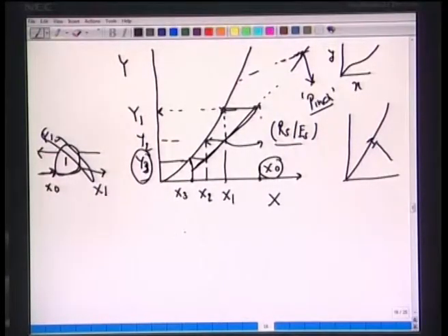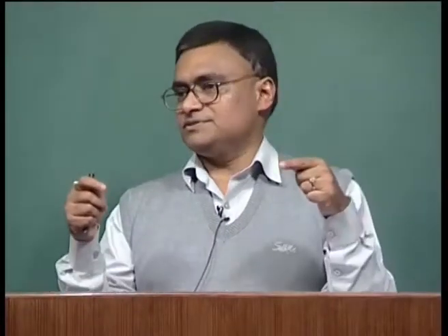Okay. We will also like to look at this entire counter current process slightly differently. If you have just one stage and we bring two streams, it does not make a difference where the inlet ports of these two streams are. So if you have one stage, they can come in contact like this, or like this, or like this.